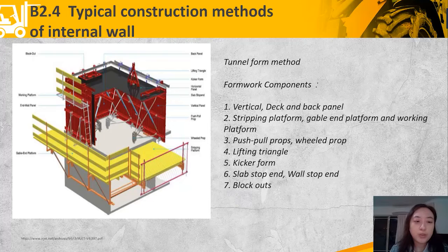There are many components of formwork, for example, slab stop end and wall stop end. They act as a stopper to hold fresh concrete up to the wall and slab line, so the project will be built quickly.